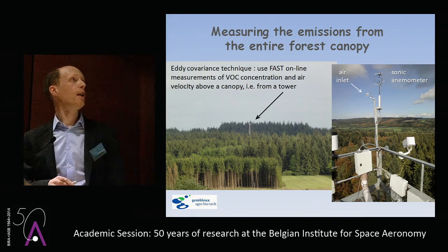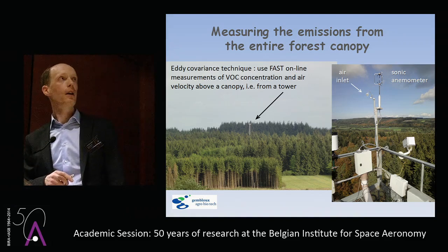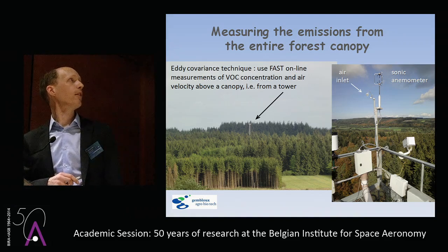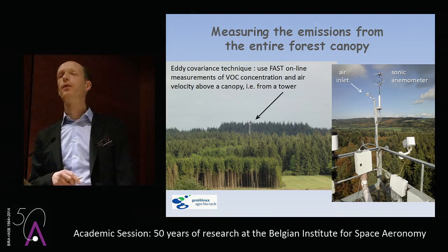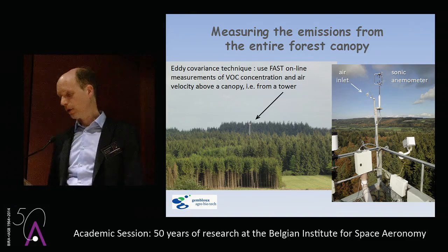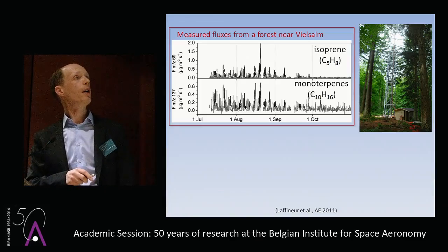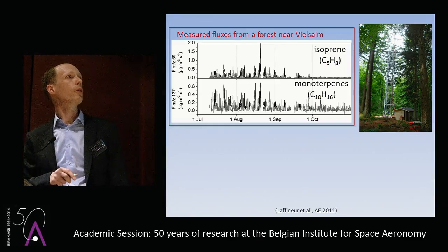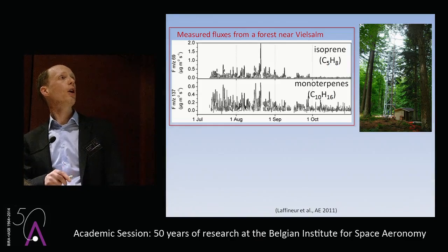And for that, we measure the air velocity, the vertical velocity, at very high frequency. And that's a very important aspect, that we need very fast online measurements of VOC concentration. So that's the air inlet, and then through tubings going to the base of the tower in this cabin here, where the PTRMS is installed.